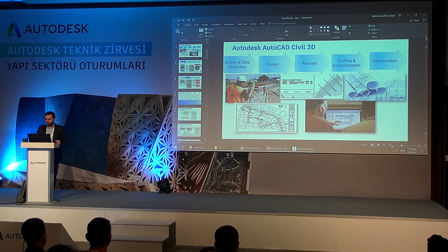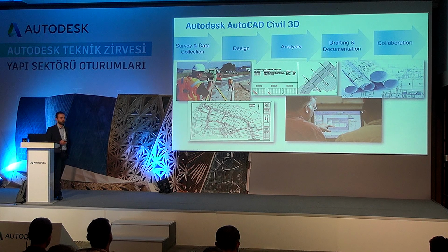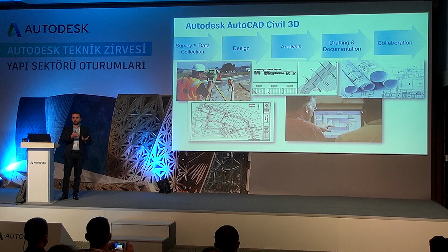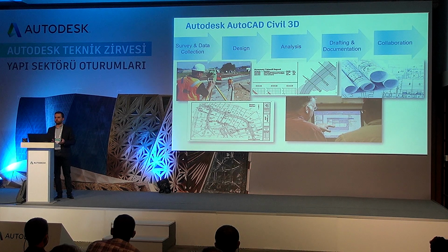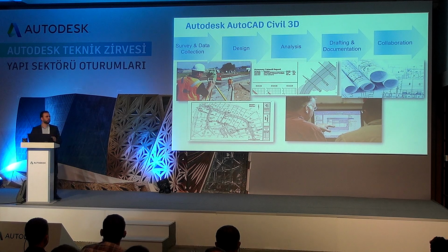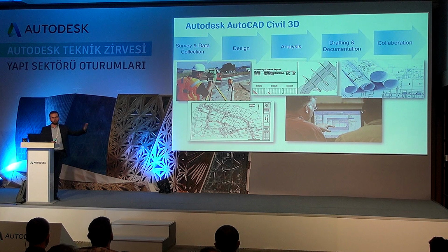Now, mostly when I present on InfraWorks everywhere, I get asked this question: because InfraWorks is highly developed, is InfraWorks going to replace Civil 3D anytime soon? And the answer is no, because InfraWorks, as you've seen, is very good, very visual, but we cannot produce any construction documents. We cannot create the plan or the sheets, profiles, and cross-sections. And this is where Civil 3D still is the right tool to do the detailed design, to get the final, accurate quantities, and definitely create all those required sheets for the construction process.